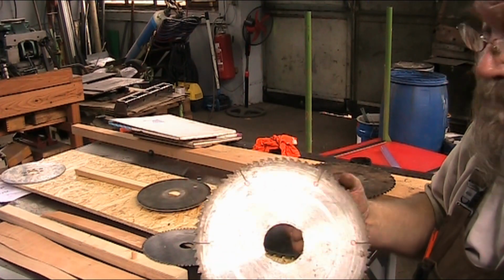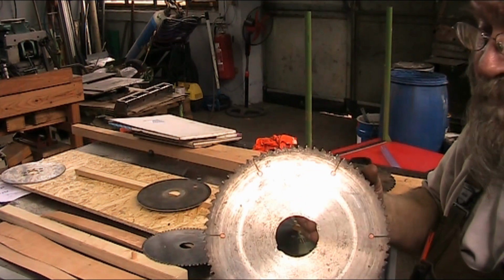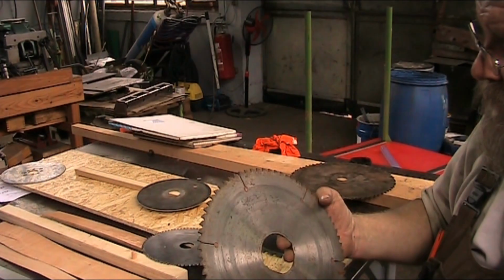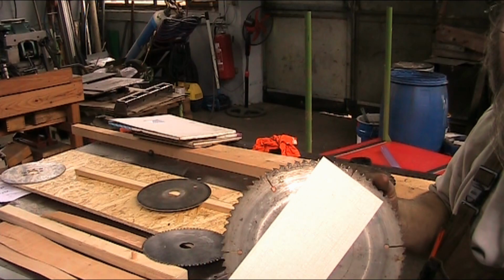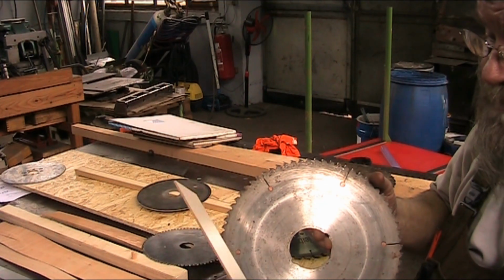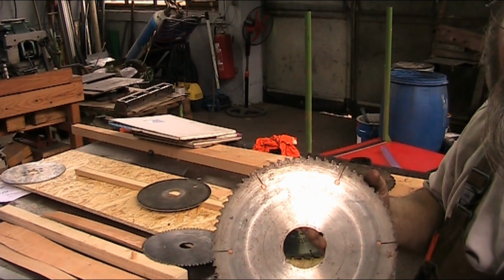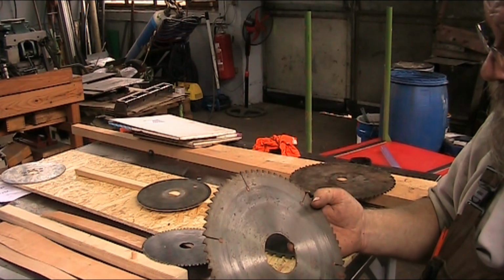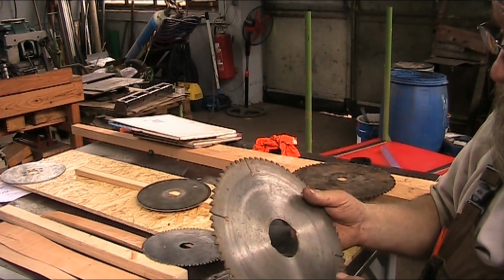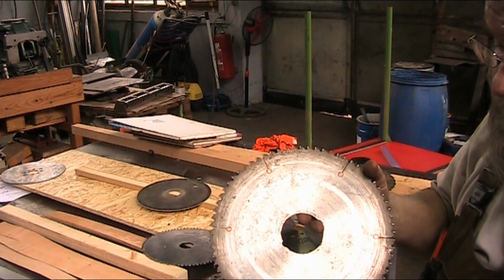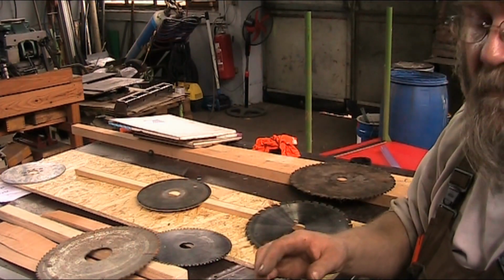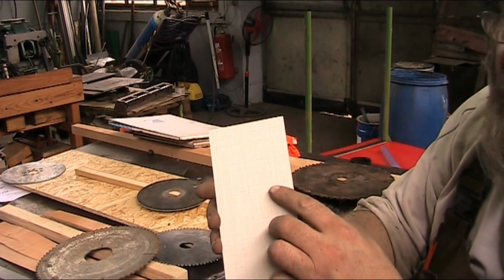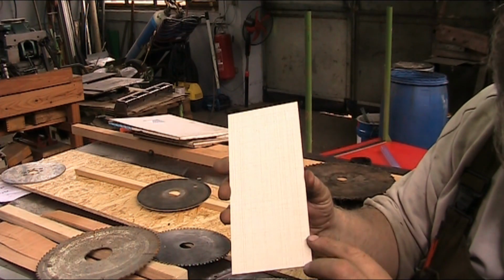The other blade that we're going to take a look at is this one here, and this blade, like I said, is for cutting this coated melamine or melamine coated material. Now melamine, as I mentioned before, is extremely hard. It's about as hard as steel, and so it's real abrasive and it's really hard on saws. So you'll see that when you're cutting, on the edge, you'll see how it chips out.